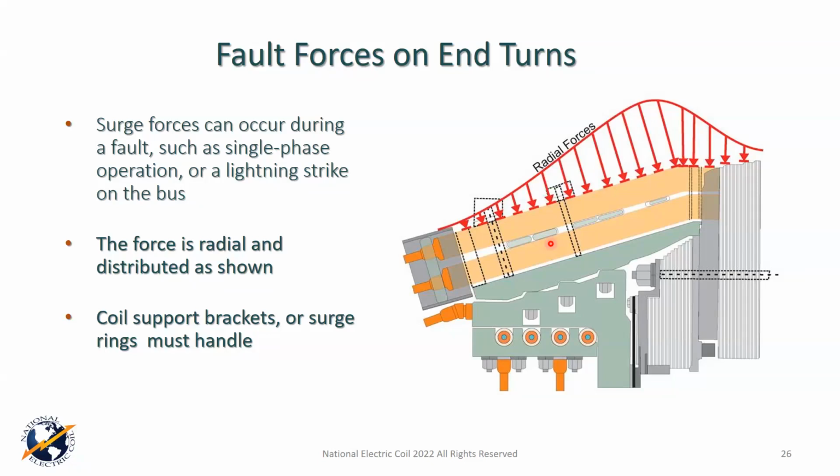One thing is you can add mass. By adding mass, it'll change that natural frequency. You can make it stiffer or more loose in some cases, not as many. Usually it's mass. But by making it stiffer, you also can change its natural frequency. And there are some other minor factors, but those are the two most common corrections for resonance.